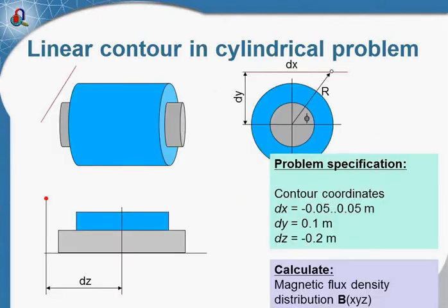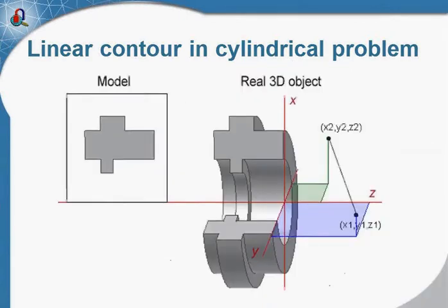But what should I do if I need to get the field distribution along a straight contour that is not aligned with the axis of rotation? I have the coil simulated with the axisymmetric formulation, but the straight contour does not conform to the axisymmetric formulation. We offer a simple tool that can convert coordinates from Cartesian to cylindrical and list the field parameters along the contour.